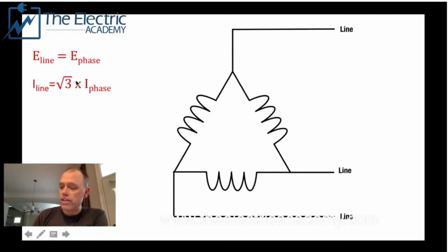Now, some of the advantages of a delta system is the motor torque. It's got high motor torque. It can handle it because it's got a higher current it can handle. It's more efficient. The protection is generally fairly simple. They're set up for heavy-duty applications. They're great for transmission. You'll often see them set up as a delta Y transformer. When you are sending power across lines for transmission, they prefer to have the delta configuration, even though the current might be a little higher, because you only require 3 wires.